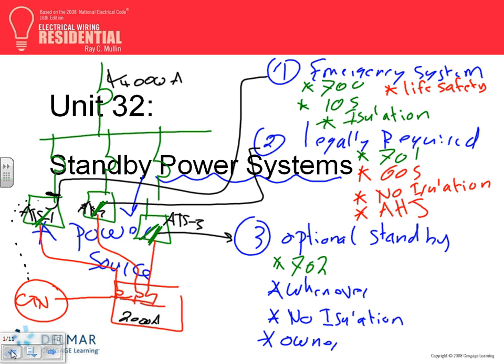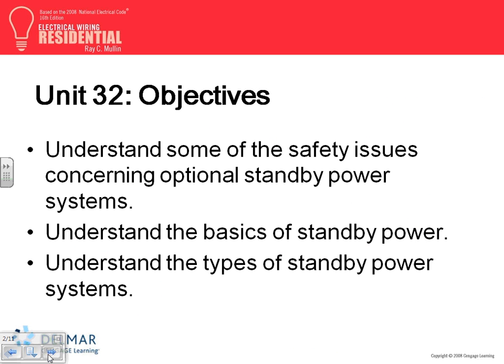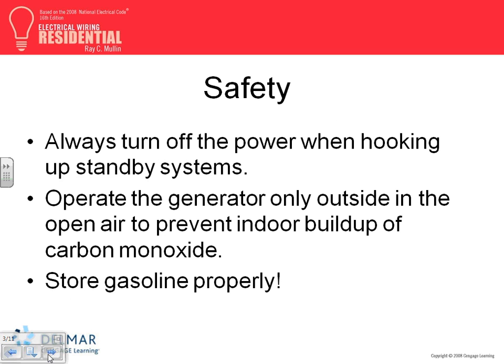You're not supposed to. I'll show you guys the alternative for this. But before we go into the alternative, let me just go over the safety, guys. When you talk about generators, as we said, always turn off the power when hooking up the standby system. That's a manual hookup, not an auto transfer switch.